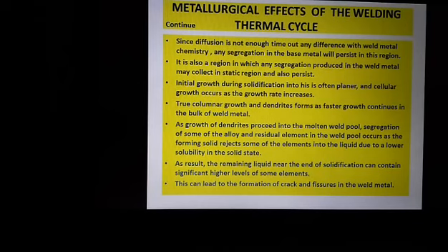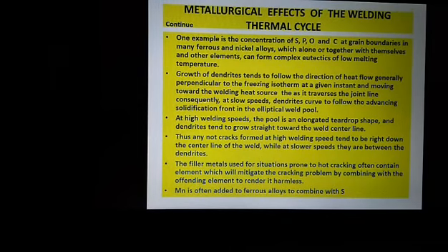This can lead to formation of cracks and fissures in the weld metal. One example is the concentration of sulfur, phosphorus, and oxide at grain boundaries in many ferrous and nickel alloys, which alone or together with other elements can form complex eutectics of low melting temperature.